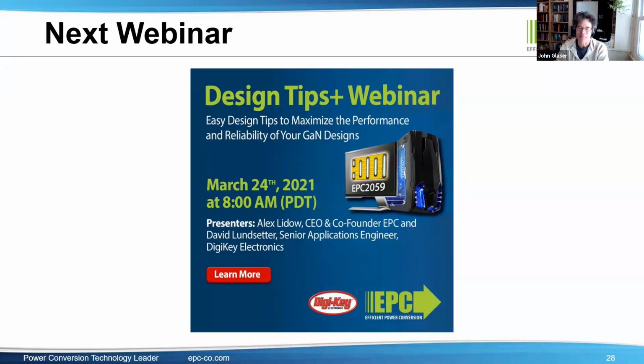It depends on how many frames per second they want. A lot of these high frequency IToF applications use an imager, and they're actually taking like a lidar video, and they can adjust the frame rate. So that's one application. Again, it still depends on the laser heating, right? In these applications, they're typically using a VCSEL. Maybe you get 30% electrical to optical. So the VCSEL gets hot. It dissipates 2/3 of the power that goes into it. So it's still, I think, limited by the laser.